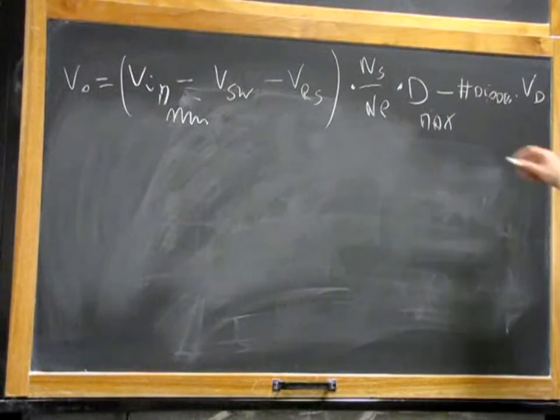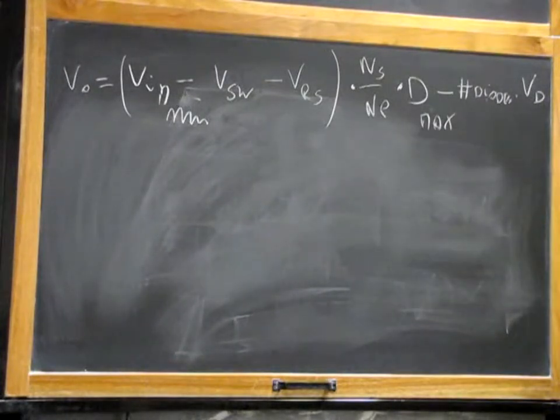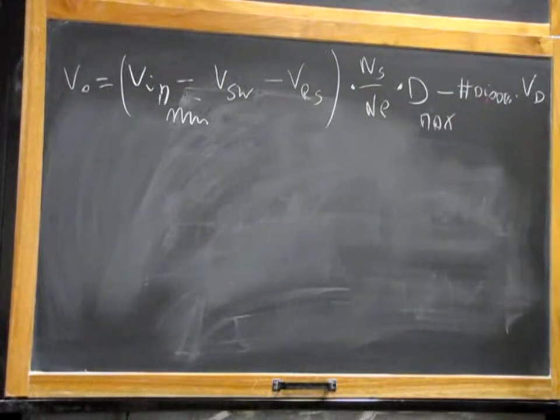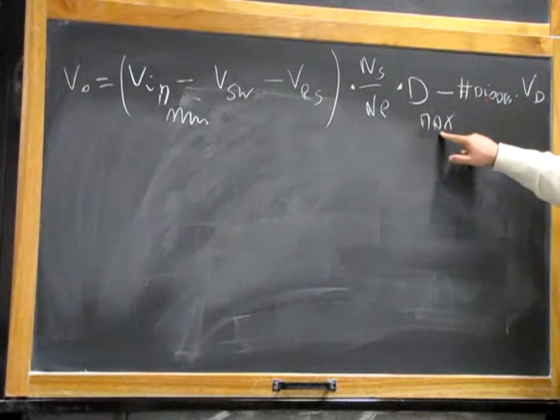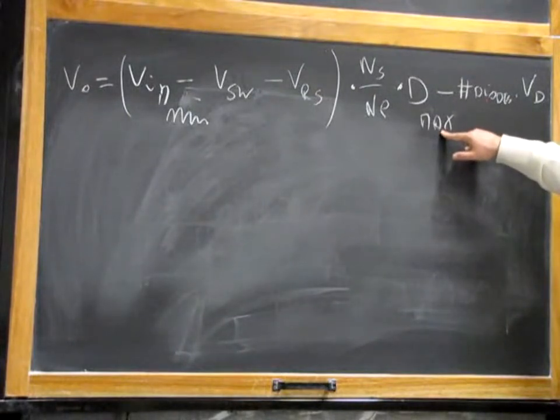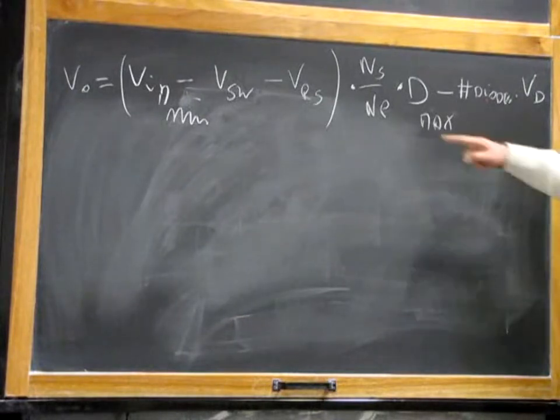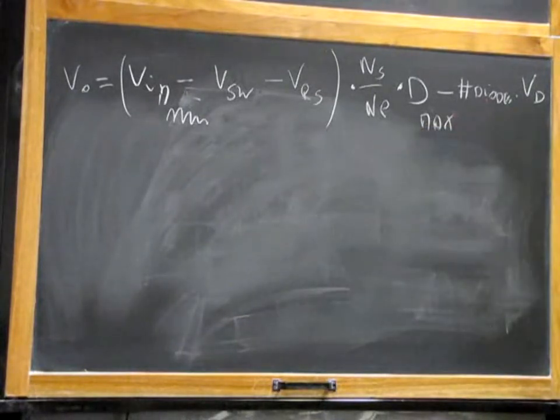So this Dmax, something reasonable but not too high, 0.8, 0.75, 0.85 if you don't have very fast changing loads. And if Dmax, this is the buck duty cycle obviously, if this Dmax is around 0.8 and you go current mode, you need for sure slope compensation. That's definitely right. What can you derive from this equation?